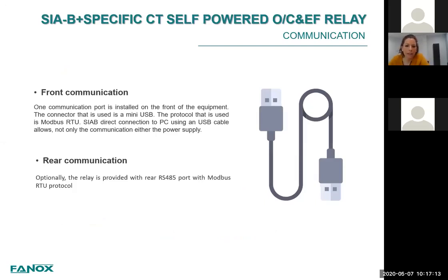And just to remark the importance of the communication in this type of relays, I just wanted to repeat that we are providing front communication through the USB port with the Modbus RTU protocol, and also rear communication to communicate with the SCADA with an RS485 port, also with Modbus RTU protocol.